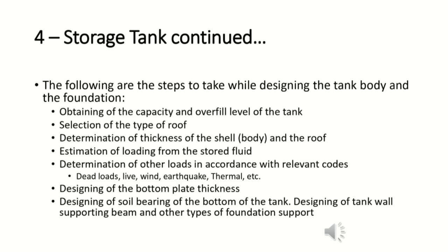Again, you have dead loads, live load, wind load, earthquake load, thermal load. 6. Designing of the bottom plate thickness. 7. Design of the soil bearing of the bottom of the tank. 8. Designing of the tank wall supporting beam and other types of foundation support.